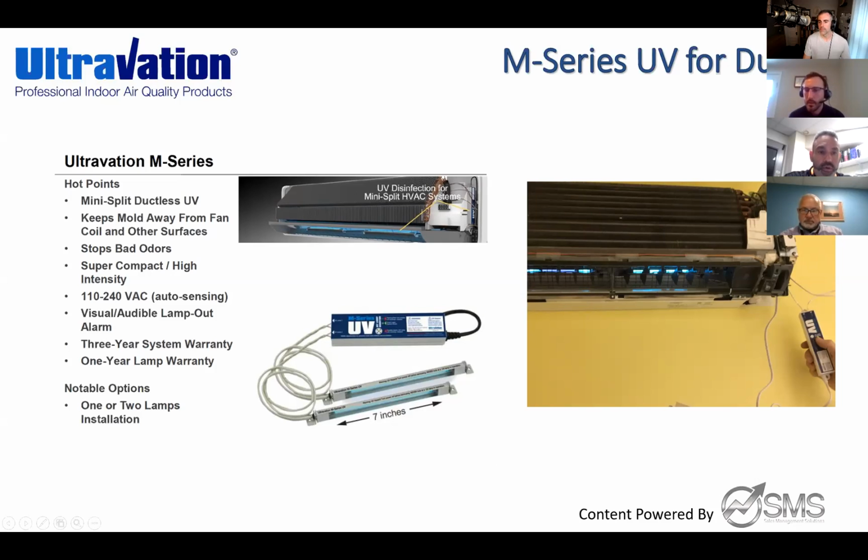So we're looking at no heat emittance out of them, right? They just rest like that because that's all plastic. Yeah, definitely. Correct. It won't damage the plastic. They do have directional shielding on them as well, so it does have a little shield. So you point that in the direction you want those to shine on. You can mount those over the blower wheel or over the coils. We typically suggest that you mount those over the coils if you can. Obviously the light can only exit from one side of the bulb thanks to the wraparound shielding.